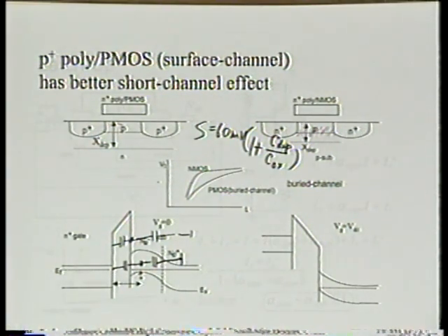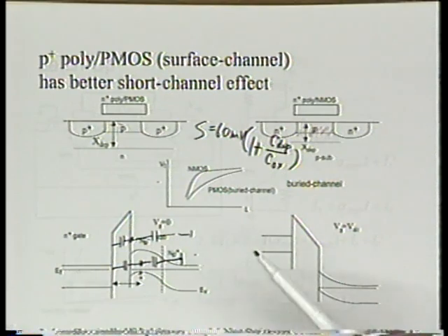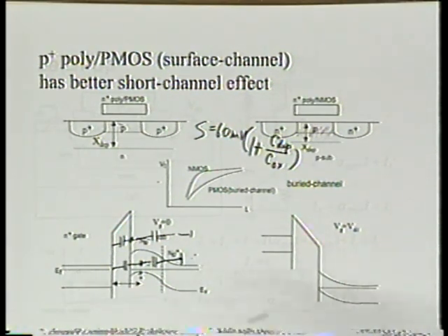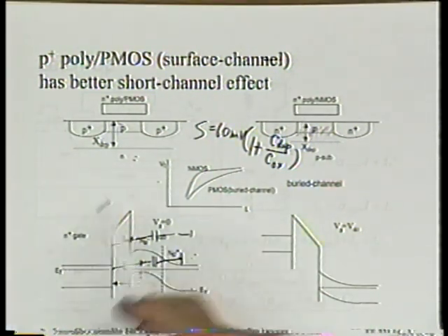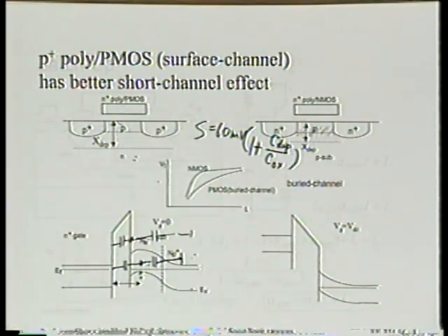Does that make sense? So when you look at this, you will agree that subthreshold characteristic is not good for this transistor either. Okay? You can try, of course, to make it good by making the depletion region even wider. Of course, you can do that by making this doping very light here, for example, or even make the PN junction very graded. And in fact, there was even an IEDM paper talking about, this is the way to design the retrograde transistor because it gives you a large subthreshold swing.